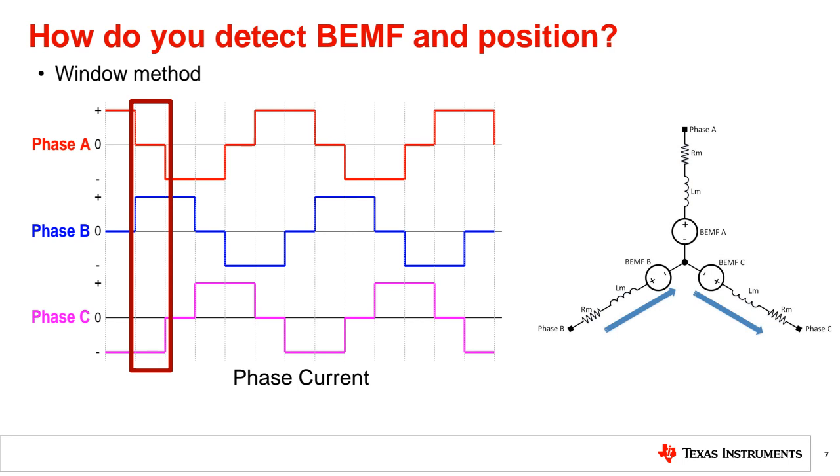You capture an analog signal and convert it to digital, and then you can convert the digital signal to real values. For example, you must calculate your motor voltage. You are using a voltage divider. Okay. Don't forget it. Some microcontrollers use 3.3 volt. Some microcontrollers use 5 volt.